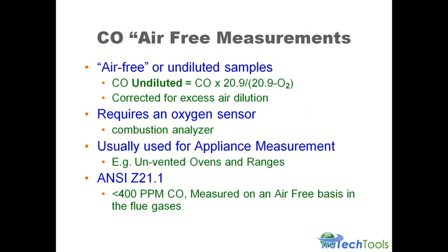Air-free measurements, we talked about that. CO air-free is simply equal to the CO times 20.9% oxygen divided by 20.9% minus the O2 left in the flue gases. It's just a formula to correct for the excess air. But here's what you need to know.